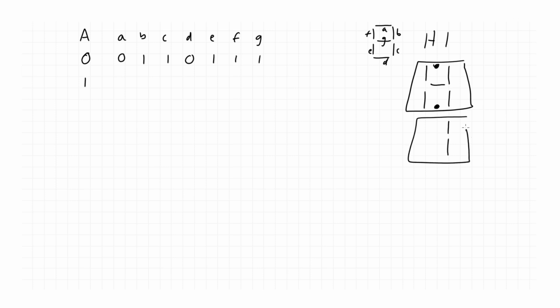Then when the input goes high, we're going to have the letter I. So the only two segments that are illuminated for the type of I that I've shown are B and C on the right. So we can put a 1 for outputs B and C segments, and everything else is 0.